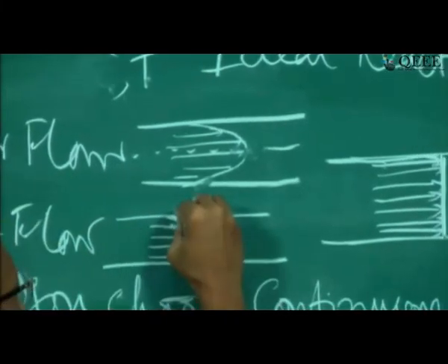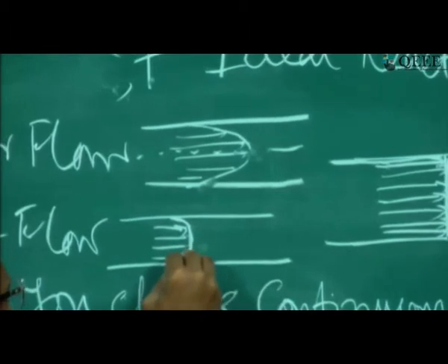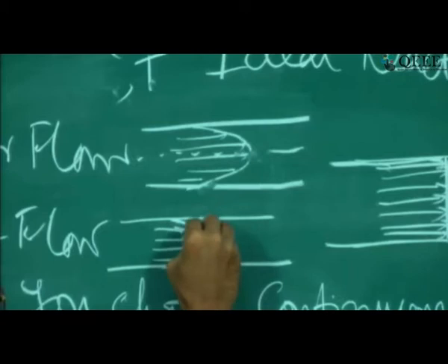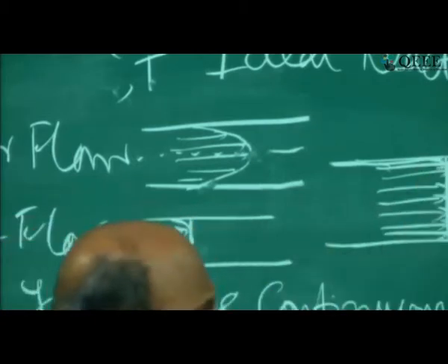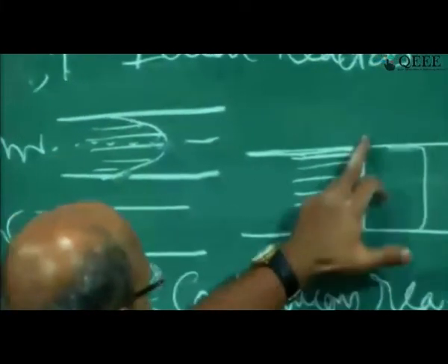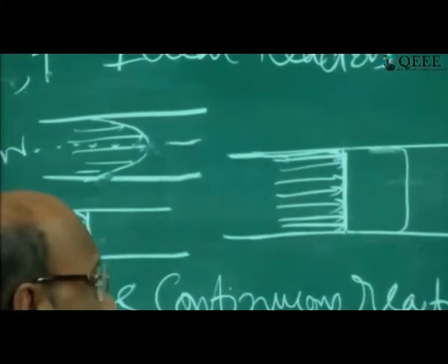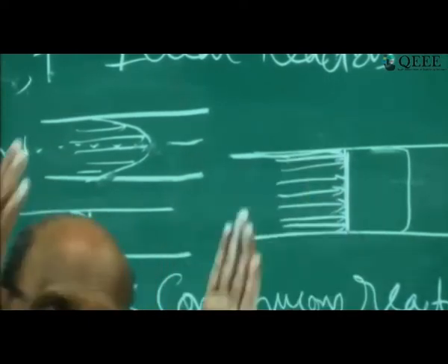Even in turbulent condition, so here if I have flat velocity profile, then each and every particle like this or like that, what I have shown, then each and every particle will spend exactly the same residence time if we assume even at the walls you have the same velocity.